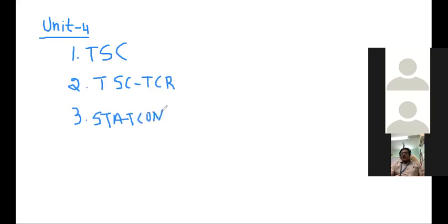Okay, I will explain one by one. First of all, the shunt compensation is classified into two categories. One is a variable impedance type, and the second one is a switched converter type. The meaning is there in that classification itself. Here the impedance is varied, nothing but reactance of this one is varied in any of these devices, whether it is connected in series or shunt. This is the classification you are considering.